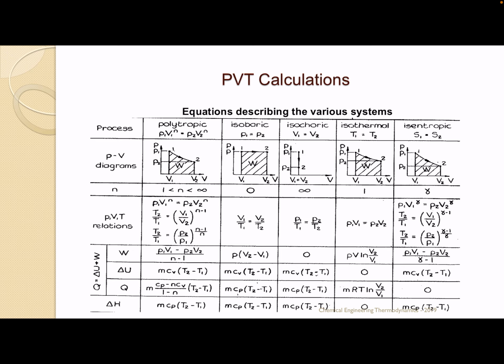And then under isobaric conditions, we've said that that is the condition where your pressure is constant. So take note, for example, if we pick a point on the y-axis, at this point of pressure, you see that the volume has changed from V1 to V2 while the pressure remains the same. And for isochoric conditions, we said that is when your volume remains constant. So hence, if we pick a volume point here, we have our pressure changing from 1 to 2. So that is for your isochoric.